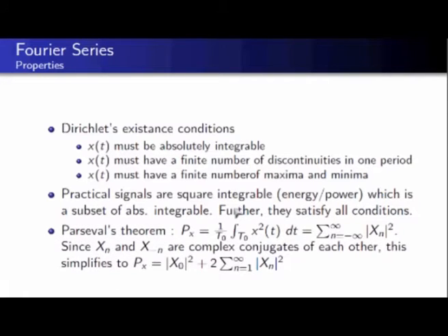Now comes the energy theorem that somebody asked, power spectrum. You can show that the power of this periodic signal x of t, I'll do this and take a break. So what I have here is the definition of power that I gave in my very first class. Power of a periodic signal is its integration over one period, square and integrate over one period, divided by the time is the power, and you can show that that's equal to summation of magnitude xn square. Xn is the nth Fourier series coefficient, 1, 2, 3, minus 1, minus 2, minus 3. So if you add them up all, infinite sum, that will be equal to power.